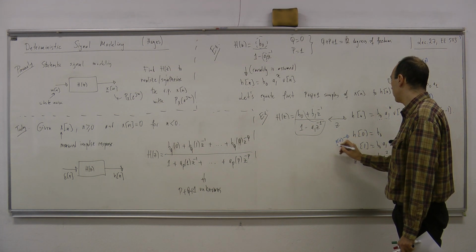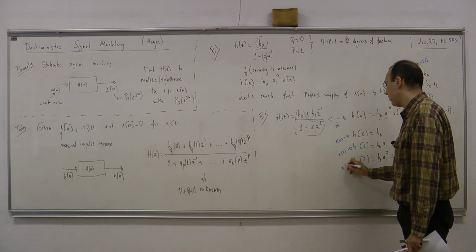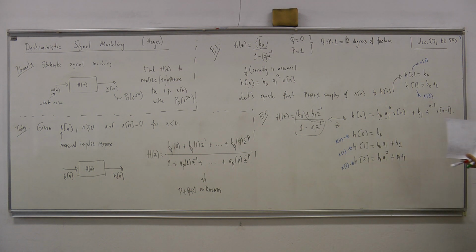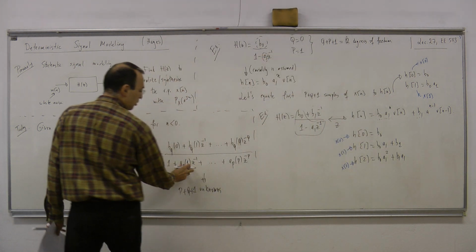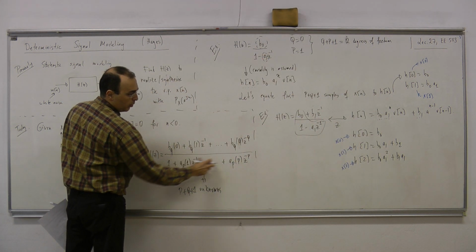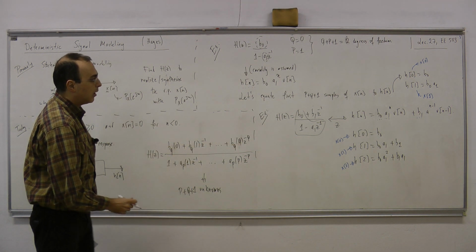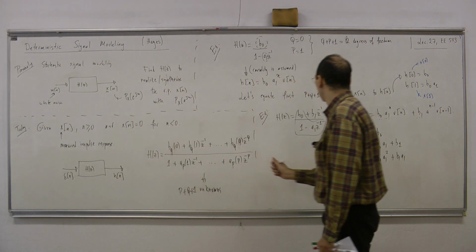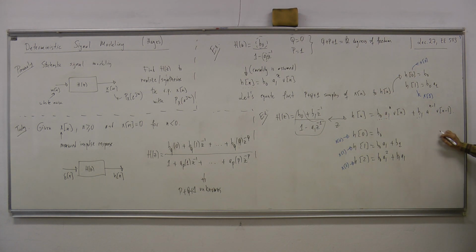Now again, this time, this is a richer model, meaning that it has more parameters. So let me equate this to x0. Let me equate this to x1, my measurement. Let me equate this to x2, and we are done. But what we see is, no surprises, we have a nonlinear equation system. Well, the obvious reason is, the unknowns are the coefficients of this denominator polynomial, and similarly, we have the numerator polynomial. And the pole zero locations of this transfer function affect the impulse response.